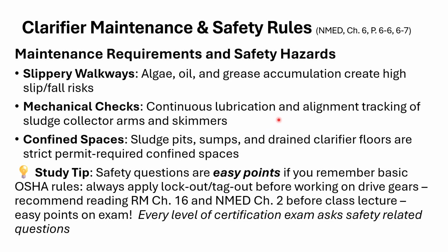You're also going to want to make sure that any of your mechanical equipment is lubricated and aligned. Whether it's the sludge collector arms or the skimmers, nothing is going to ruin your day more than hearing a screeching halt of metal against metal. If you don't have enough lubrication, or if something's misaligned and just starts rubbing metal against metal, you're going to break something, and it's probably going to be expensive and hard to repair.